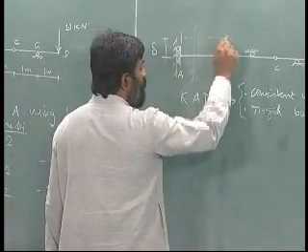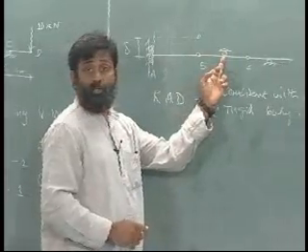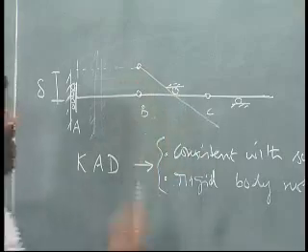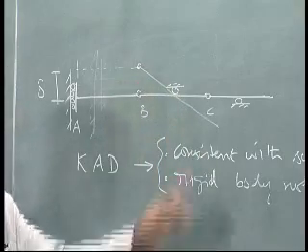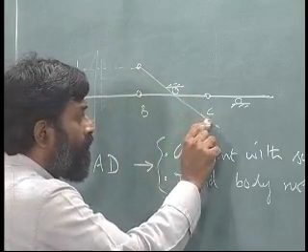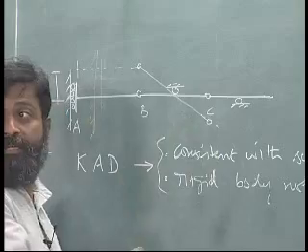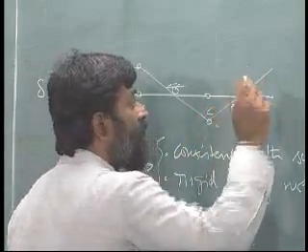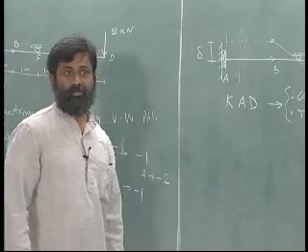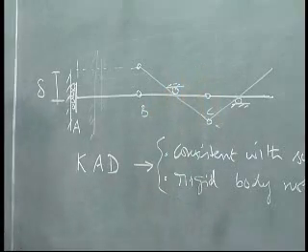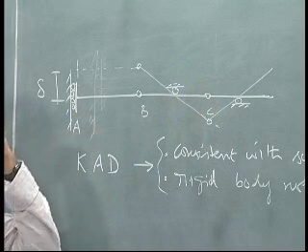At this point what should happen? This will not allow movement, which means the only way possible is going along this. So the point C has to move down like this. Now at point C again this will not allow vertical movement, which means the only way possible is a displacement like this, very simple. Geometrically if I draw it, it will make it simple. The moment I know this I have solved the problem.